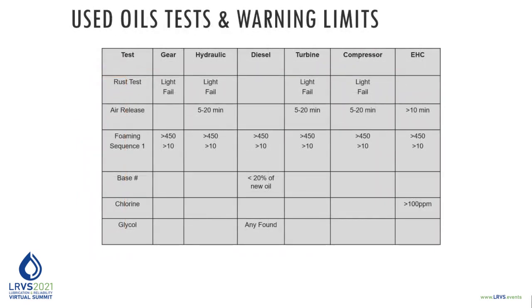Here's another example of a used oil warning alarm table, taking a look at other test parameters as well. Rust, air release and foam sequence, base number, even chlorine and glycol concentrations, and setting up alarm limits accordingly.